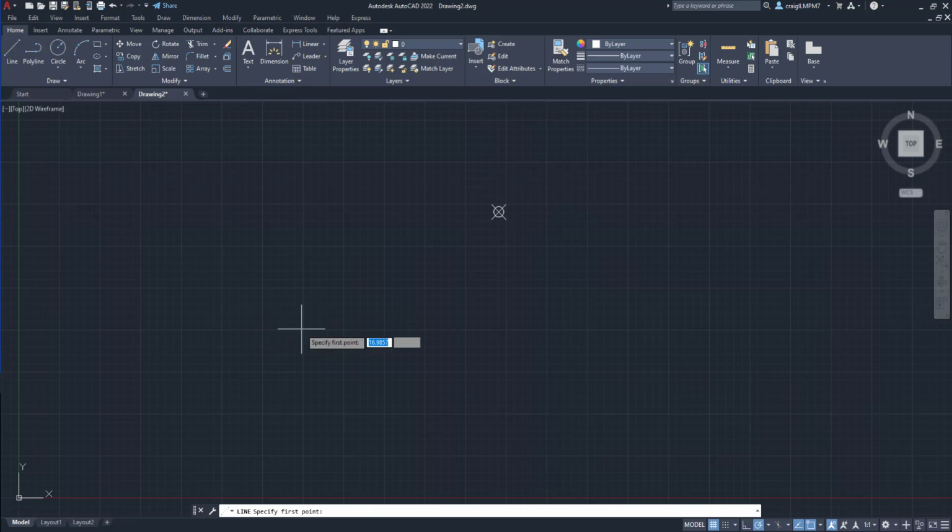So you can use the mouse and specify your first point. It wants you to tell it how long. So, you know, you can tell it 9.2 or something. And then over here, notice that's where we entered our units for the length. Over here, it's got a degree.